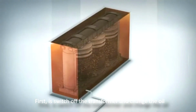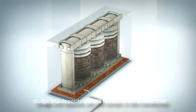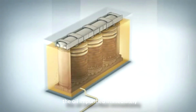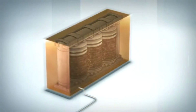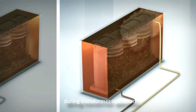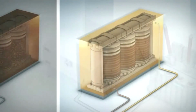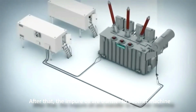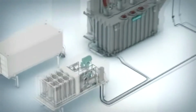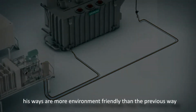First is to switch off the transformer and change the oil. But while the oil is being changed, sludge and deposits still remain in the transformer. When the new oil is filled in, the oil is immediately impure. A better result can be achieved by regenerating the oil during transformer operation. The new oil is pumped in and the impure oil is removed at the same time. After that, the impure oil is transferred to another machine. This machine cleans the oil and makes it ready for reuse. All processes and data are monitored. This way is more environmentally friendly than the previous way.